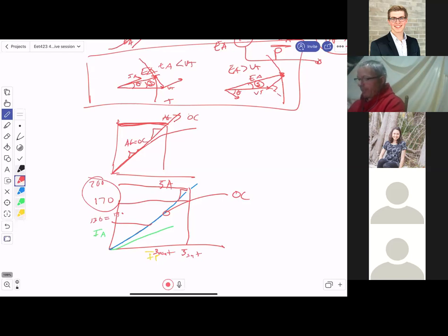So another thing is, let's say to get 480 volts here on the air gap line, it takes 15 amps. To get to 480 volts here, let's say it takes 20 amps. Then you know to get to 480, you have to operate saturated, because your air gap line is not physically realizable, but the open circuit characteristic, you have to drive it at a higher field current to get there. So you can even look at it from a perspective of field current to see if you can get the same voltage. So it's either way, it's the same thing. Does that clarify?